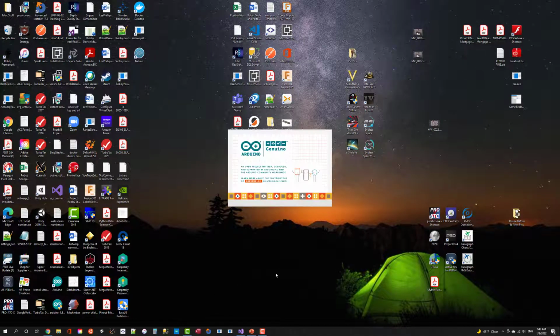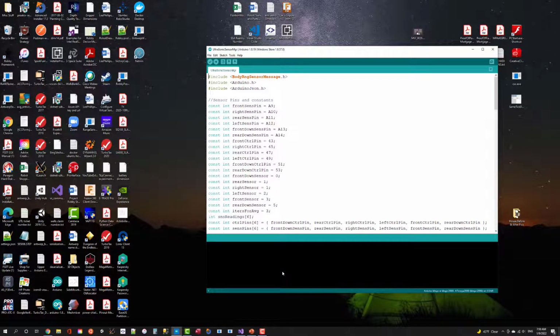Before we start actually digging into the framework, let's talk a little bit about what I'm going to show you. I've got an Arduino Mega board here with nothing attached to it except the computer that we're looking at, but it does have a little script running on it. This script is one we actually use in the robot project we're working with currently, called Antwerp. There's not really a lot to this little sketch. All it does is get readings off of half a dozen analog pins here and send them out in a JSON package on its serial port.